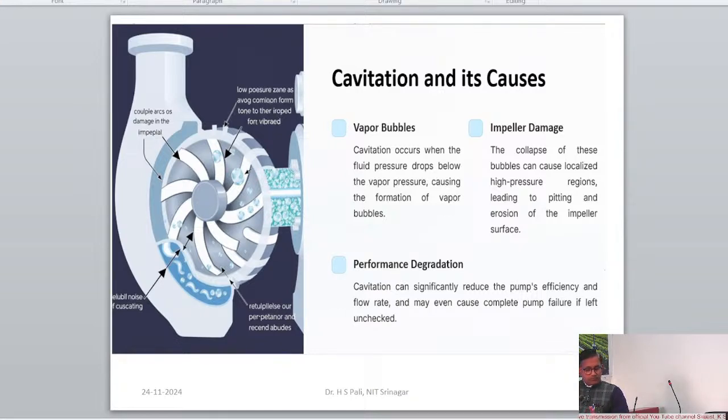The power output of a pump is defined by the formula rho Q H, where rho is the density of water, Q is the flow or discharge, and H is the head. So this is the power of any pump. This power can be defined in the performance curve. The flow rate is how much water the pump can move. So what do these charts represent?